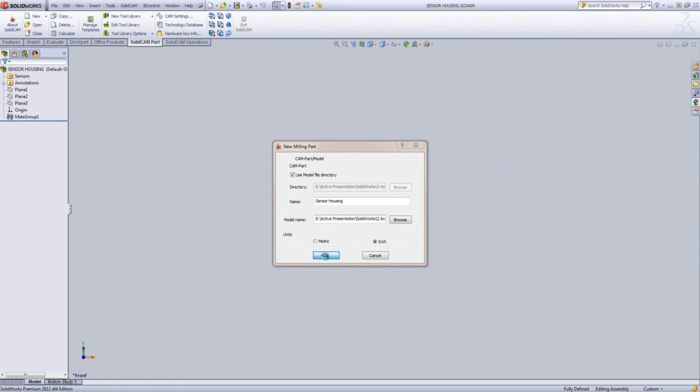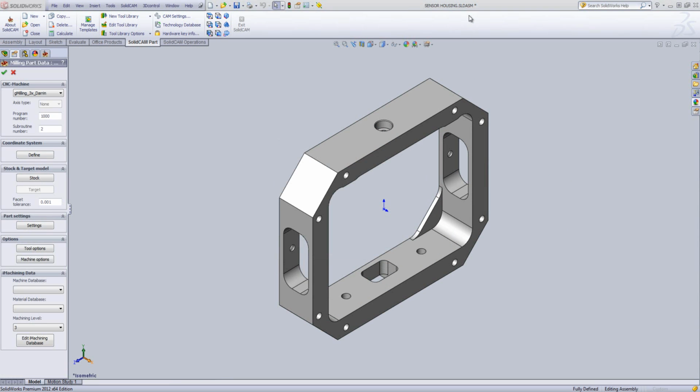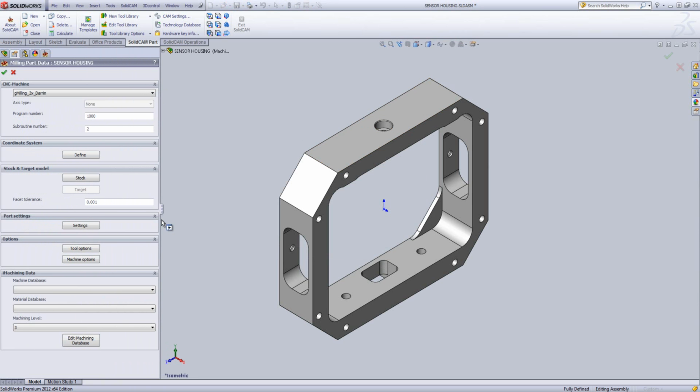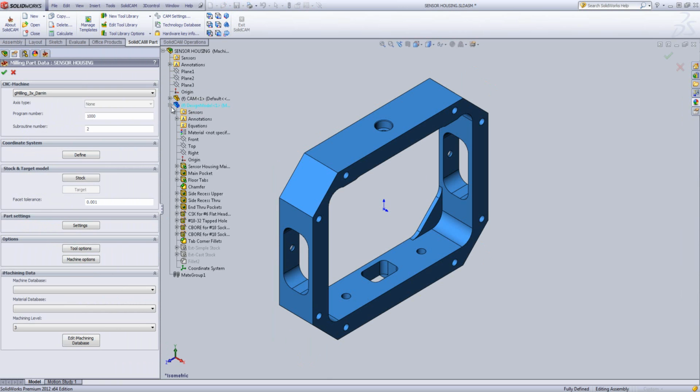The first thing that happens is that a SolidWorks assembly is automatically created, and we are now running in assembly mode. The second thing that happens is that SolidCAM created a perfect copy of the original part and put the original part away for safekeeping. The copied version of the original SolidWorks file is called the design model. Any revisions to the original SolidWorks model will be automatically propagated down to the design model, provided that the option was set in the SolidCAM settings.